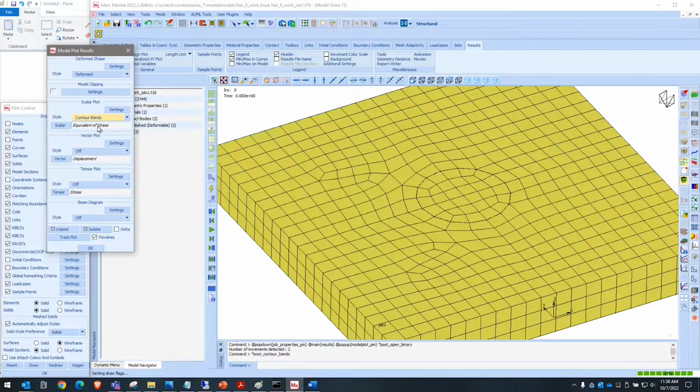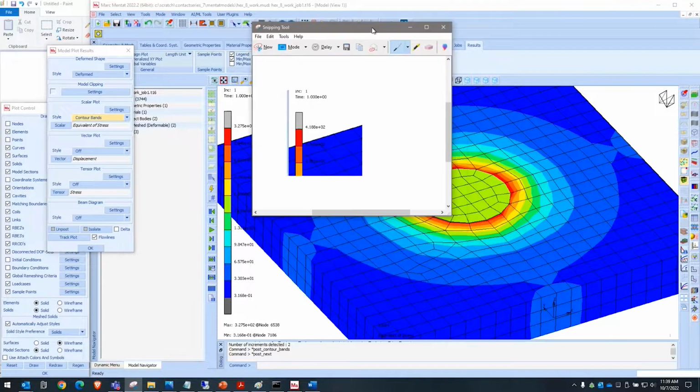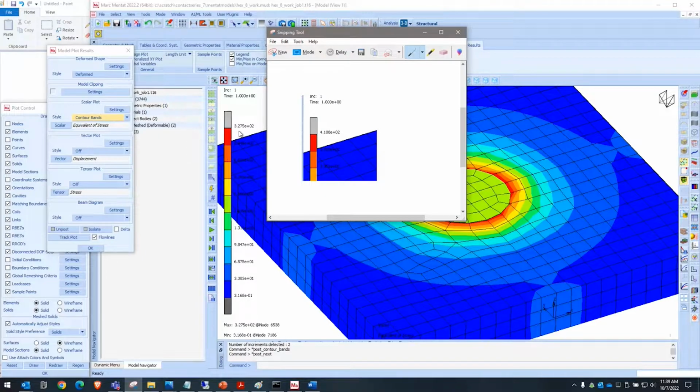Can we look at the stress state again? And now I see something is not perfect, so there's still a slight variation there, but that can be due to the element distortion and shapes and so on. But this is an order of magnitude better than the previous result. I take that snapshot from before, it changed from 420 MPa to 330 MPa.